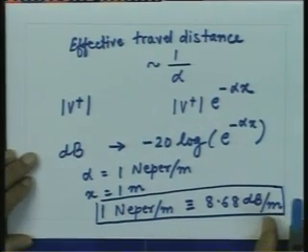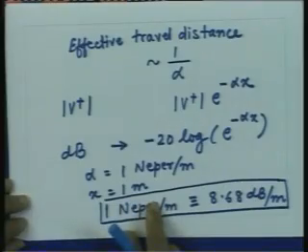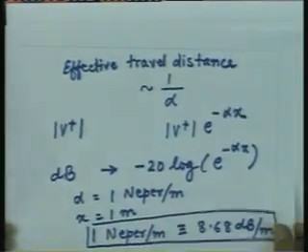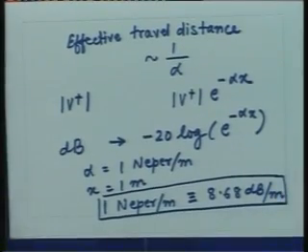Again, as you have seen in terms of the phase constant, the attenuation constant also is a function of the primary constants or the line parameters, and also it depends upon the frequency. So, in general, the propagation constant, which is a combination of phase and attenuation, is a function of line parameters and it is a function of frequency.